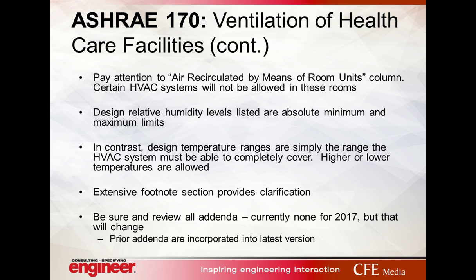There's an extensive footnote section at the end that you really do need to read through and be familiar with, because it clears up the ambiguities of the chart. And be sure to stay on top of the addenda. There were several addenda issued to ASHRAE 170 2013, and all of those were incorporated in 2017, but once they're published, they're part of the standard. So I don't think there are any addenda for 2017 yet, but there will be, and they will also be binding. Those are free to access on the ASHRAE website, so you can always go and check. You should do that at the start of every project.